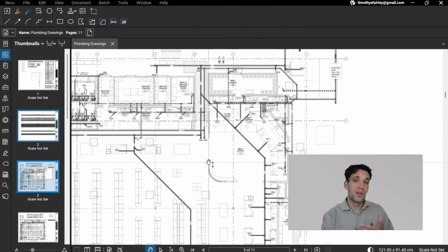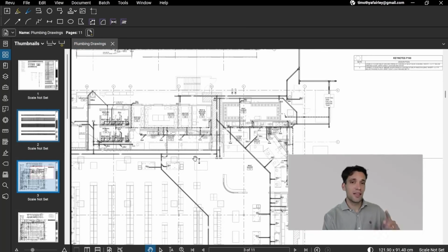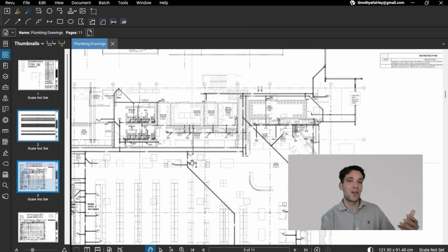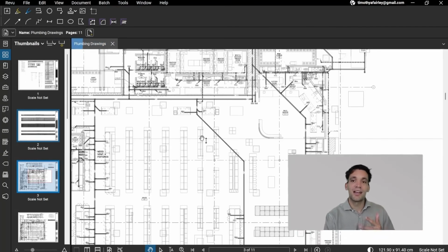The only thing we would have to be aware of is when there are changes in heights. For example, we have a vent stack going to the roof. We obviously need to factor in that some of these pipes will be rising vertically, so we can't simply measure the lineal meters on a 2D representation of a plan view.